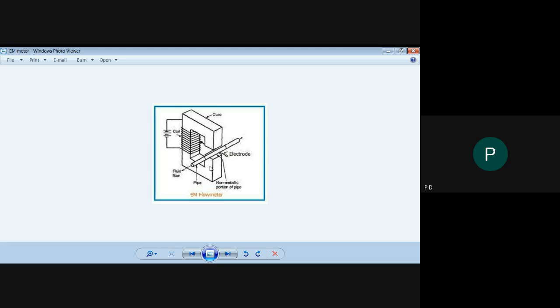आता याचे ॲडव्हान्टेजेस काय असणार आहे? It can be used for any type of conductive fluid for long distance flow measurement, म्हणजे जिथे तुमचं पाईप साईज पण इन्क्रीज होते, लार्ज पाईप साईज असेल तिथे पण तुम्हाला यूज होतं. त्यानंतर ॲसिड अल्कलाईन टाईपच्या फ्लुइड्स जे असतात त्या मेजरमेंटसाठी तुम्ही यूज करू शकतात. आणि इथे काय, हा इनडायरेक्ट मेजरमेंट मेथड आहे, meaning there is no direct contact of any human being. हा इनडायरेक्ट मेथड आहे which is very advantageous as compared to the previous one.